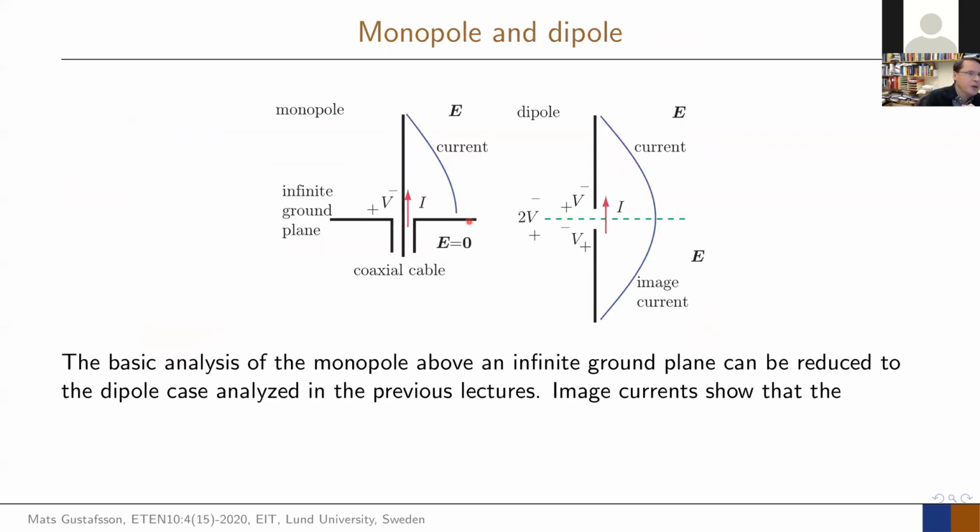So now we should do then the monopole. So the monopole antenna was this then half dipole that sticks out of the ground plane. So let's assume that it's half a wavelength. It doesn't have to be, but let's assume that. So if I have my dipole to start with, then I have my dipole antenna here. So we will have a typical length of this L. And then we can have a current that goes down there, and we know it's resonant when it's half a wavelength.